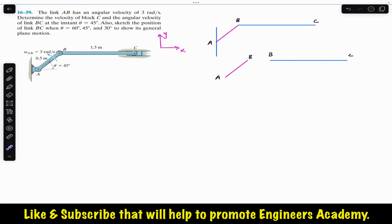As I have discussed, when this link AB rotates in the counterclockwise direction, this point C will move towards the left. So we can show that VC here. This is link BC, the free body diagram of link BC. So we will have VC, the velocity of block C, towards the left.